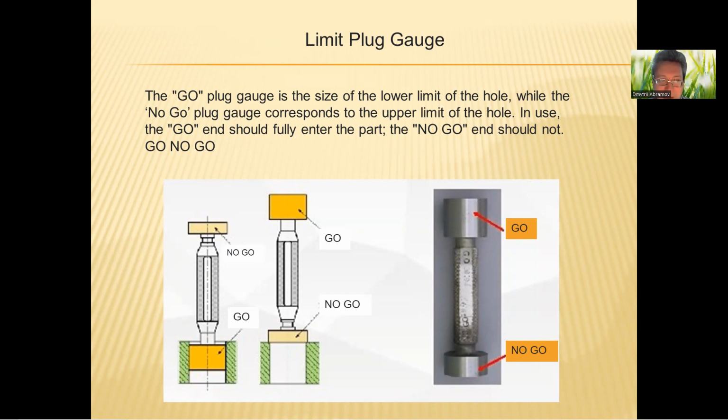In use, the go end should fully enter the part, like in this figure. The no-go end should not, like in this figure.